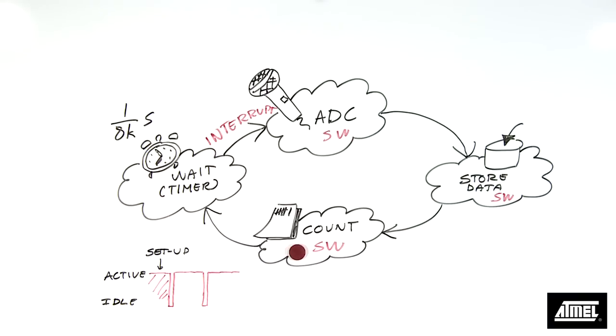The activity curve shows how the device jumps back and forth between active and idle modes throughout the entire recording period. Most of this is handled by software, so the CPU spends a lot of time in active mode. The only idle state is the wait state. This of course impacts the power consumption. Also, the CPU is mostly busy here and not available to do other things.